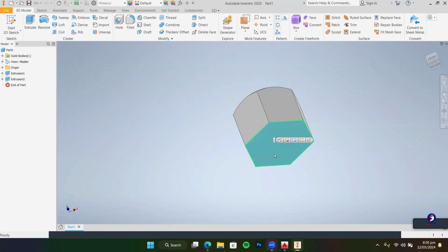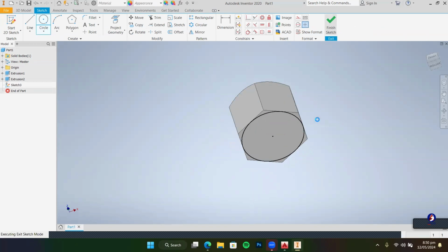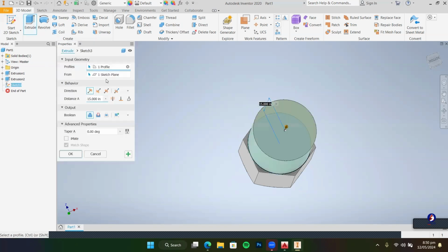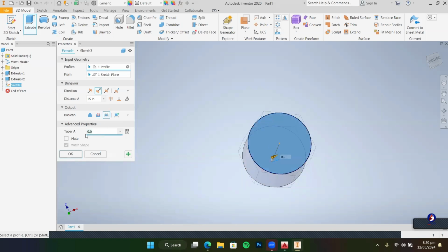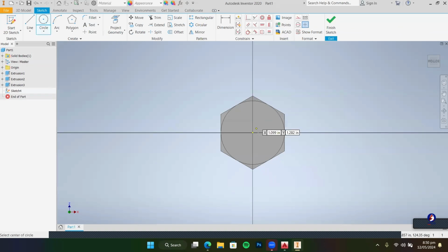So I'll select this face, right? Start a sketch at this face. Pick my circle to locate my center and draw it to touch it. That will be my tangent for now. I'll just rotate it like this. Select my extrude, flip it to the other direction, and select intersect like we selected for the AutoCAD. We will type the angle 45. Press OK. We are done. I can select this face again and create a new sketch. Select my circle. We selected 10, right?